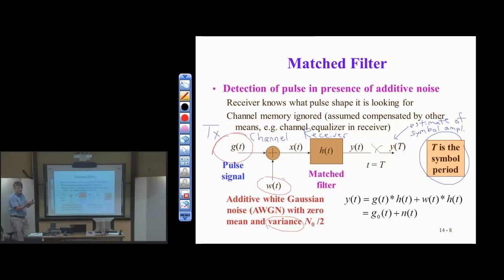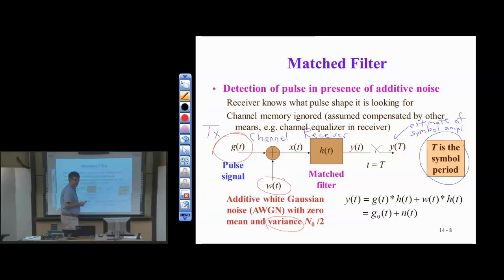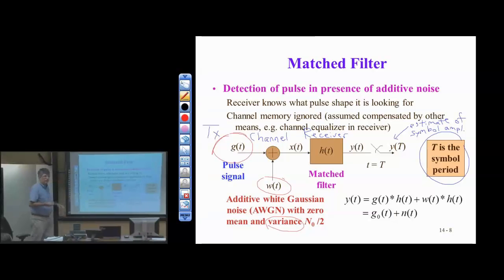Go ahead. What is special about the match filter? We will derive that today. What is so special about the match filter: if you design it right, you maximize the signal-to-noise ratio at the output of the sampling block. Now, that's important for a couple of reasons. One is that the detection probability is going to vary with SNR.